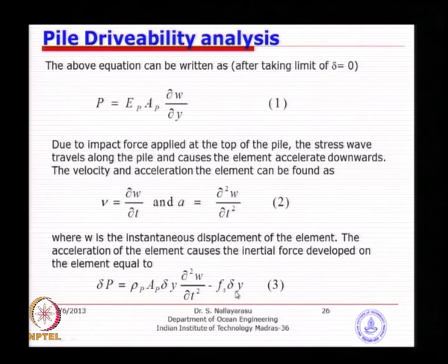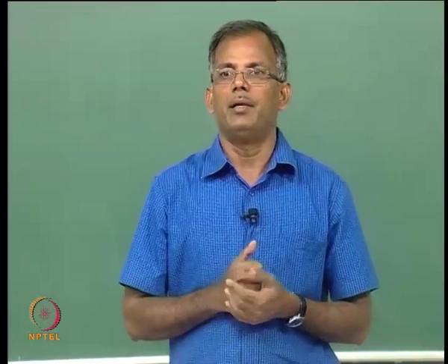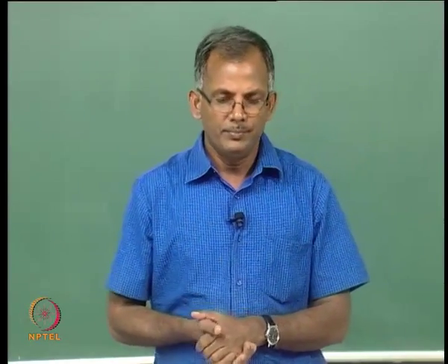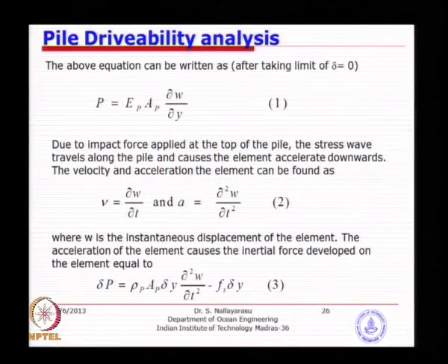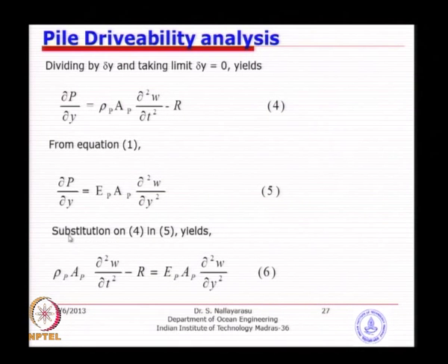Of course you can have your pi d multiplied if you have a circumference. So this is the resistance offered by the soil, that means every time the pile is trying to accelerate, the resistance is provided by the soil in terms of skin friction, and if you integrate you will get a value, just a notation change, and that is what is appearing here. Now if there is no resistance, that means it will just keep going down. So that is the equation that we were looking at.